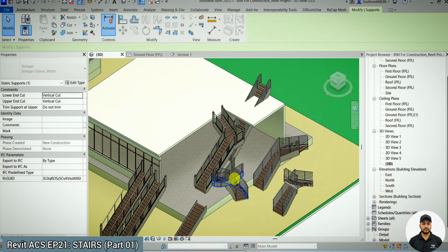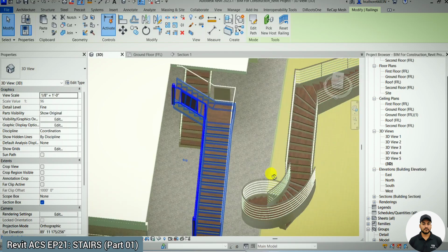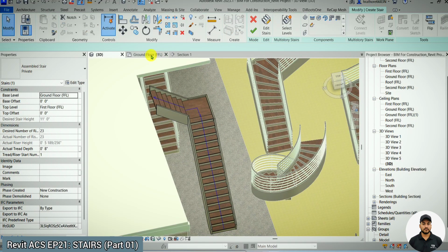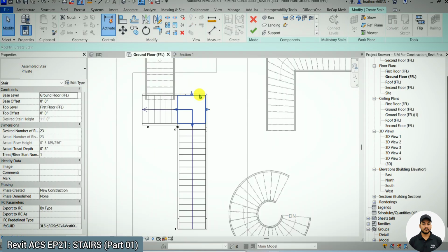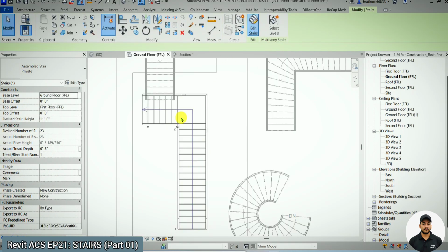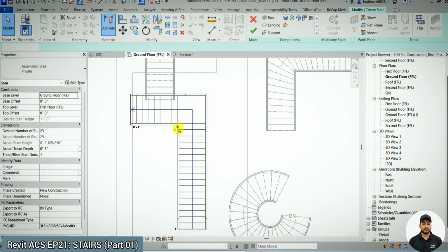Okay, so as you can see here, we have created an L shape. This time we have a landing at the connection of both the risers. Also when you are editing, if a landing is not created automatically, then you can use this feature. You simply go here, pick the first one, and it will ask you for the second one, which you select. It will create a landing. And if you want to increase the size of the landing, you can simply move it more to the front, and like that you can control it.